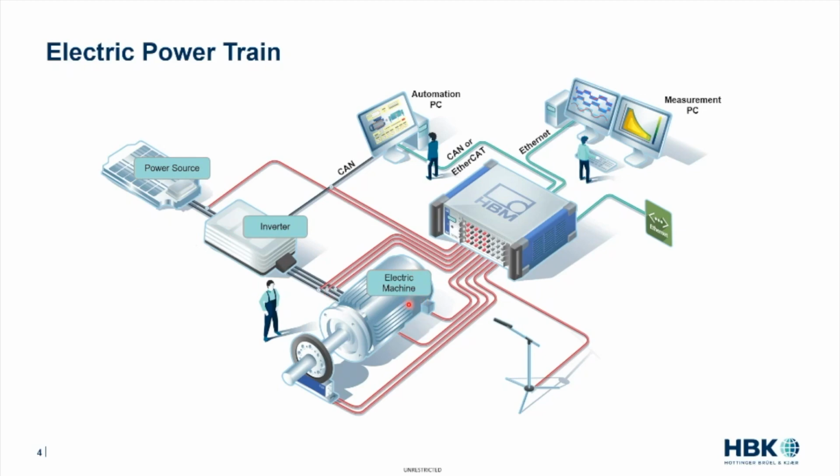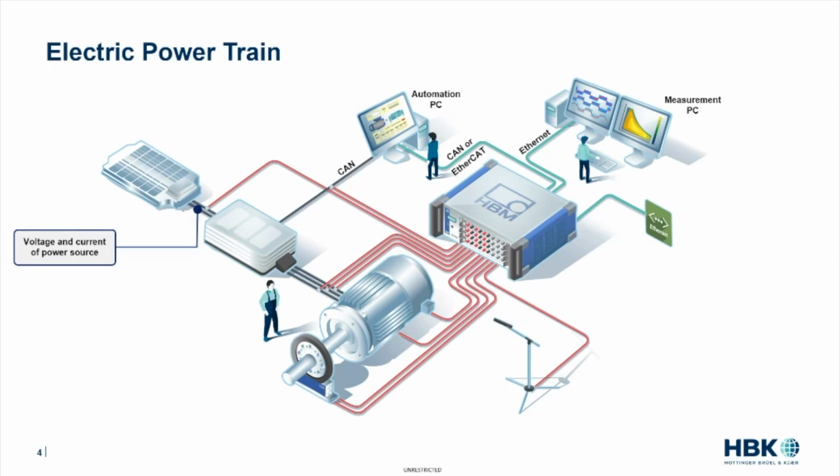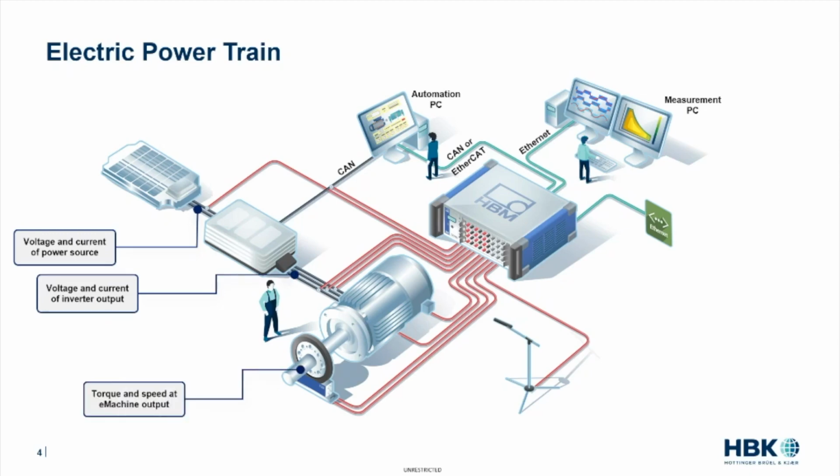In order to understand that drive, you at least need to measure a few parameters, typically voltage and currents out of the power source, voltage and current from the inverter into the drive, and obviously the mechanical parameters, torque and speed, out of the drive.